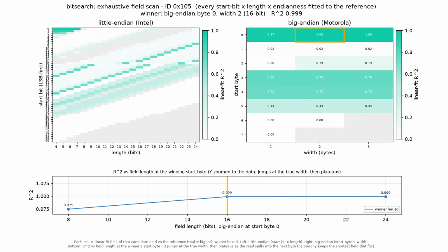And from this analysis, Claude will typically get a few candidate potential signals, and it can then do the next step, which is a bit search. And here Claude does essentially all of the potential variations of bit start, bit length, endianness, signed, unsigned, all of that stuff in a lot of iterations. And again, the idea here is to correlate and identify which of these combinations will give the best match against the reference signal that it is provided. Once it has done this exercise, Claude should have essentially the relevant bits of the signal that we're trying to reverse engineer.